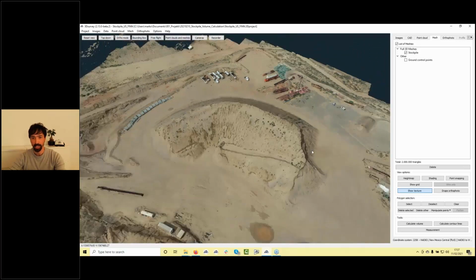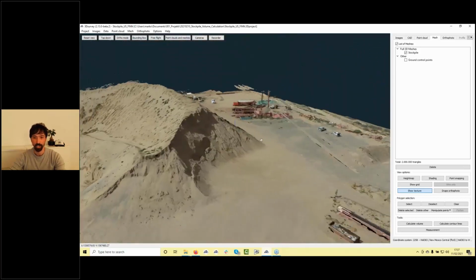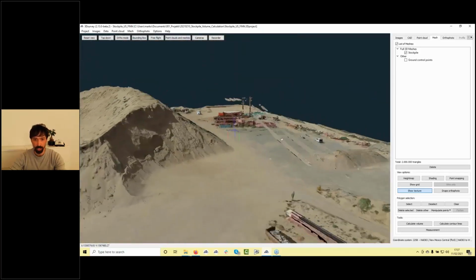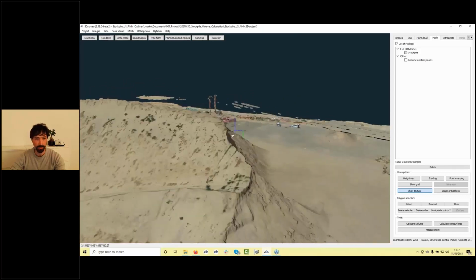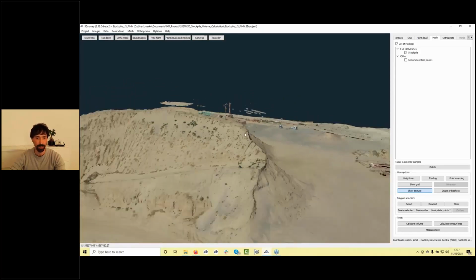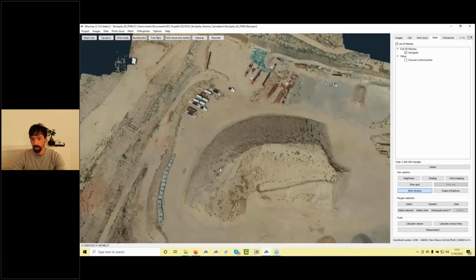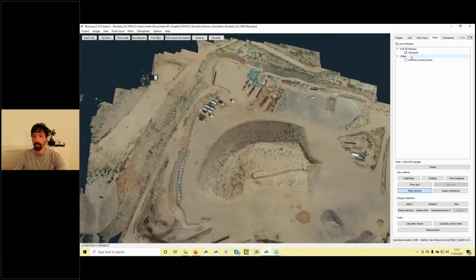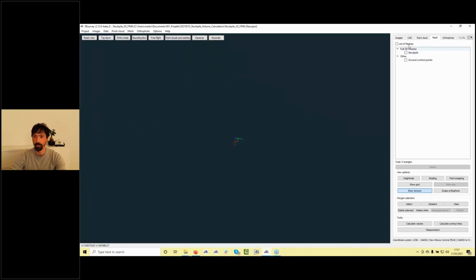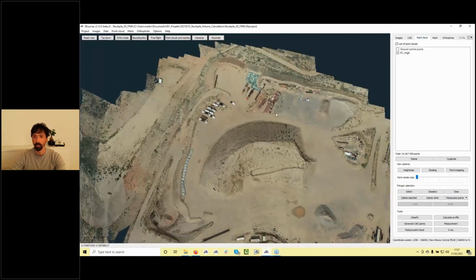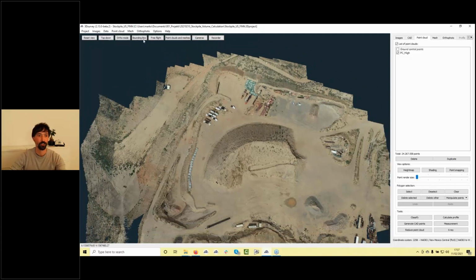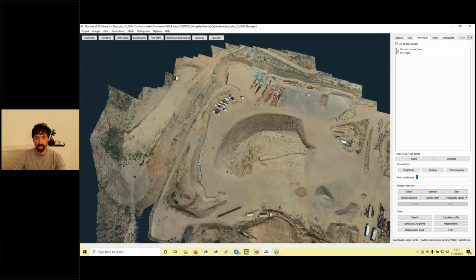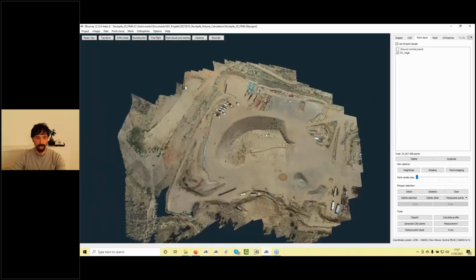Why? Because in a full 3D mesh, you can maybe get some kind of balloons like in cables here. This can happen maybe if there is high grass or something like that. Of course, it also works if you would like to calculate it, but we advise you to turn off the full 3D mesh, go back to the point cloud and calculate a regular grid mesh. So the option is here, but before we do this, I will also do the classification.